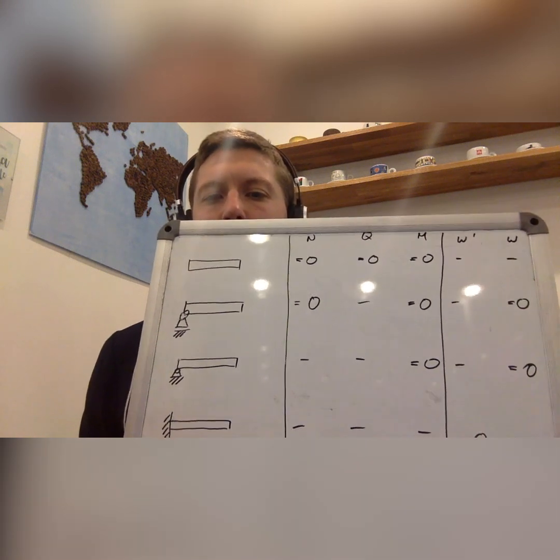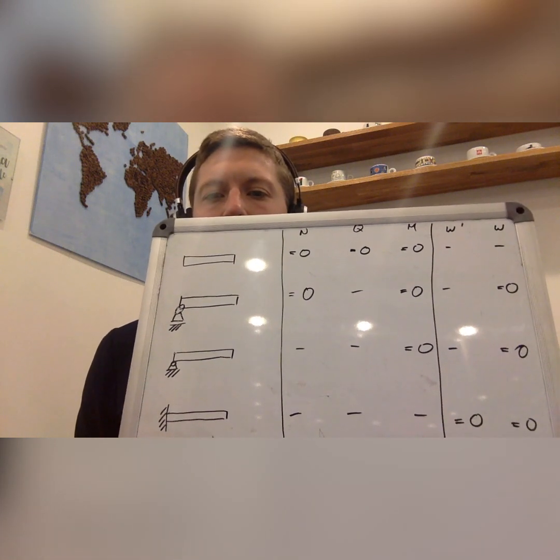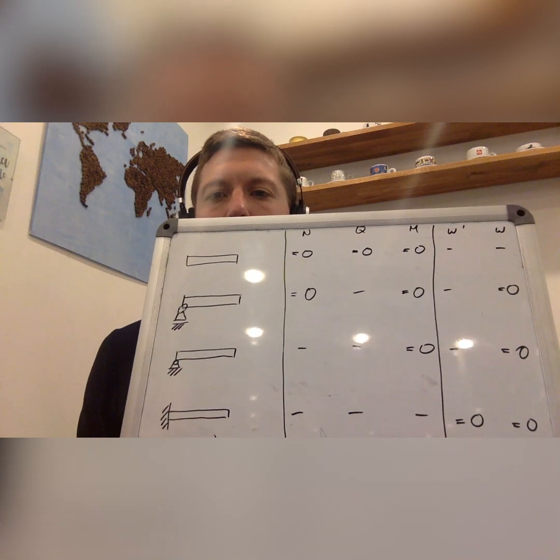And as already mentioned, this prevention of w and w prime means that you could have normal forces, shear forces, and bending moments which are transferred via this bearing type to the environment. So if you would make a free body diagram, you would enter here a force in x direction, a force in z direction, and a bending moment, a bearing moment, and they would just balance the internal loads of the beam at this position.